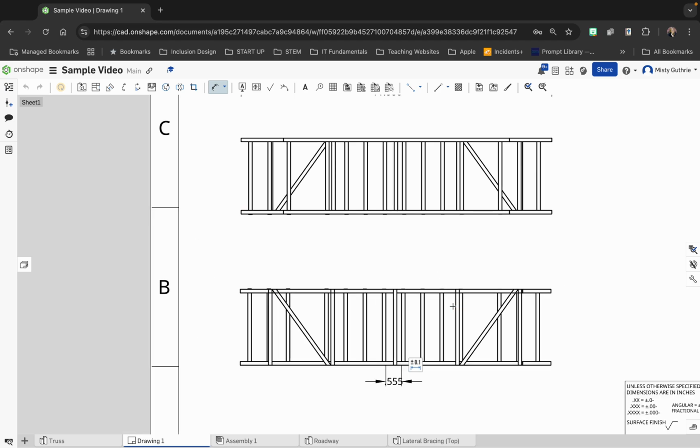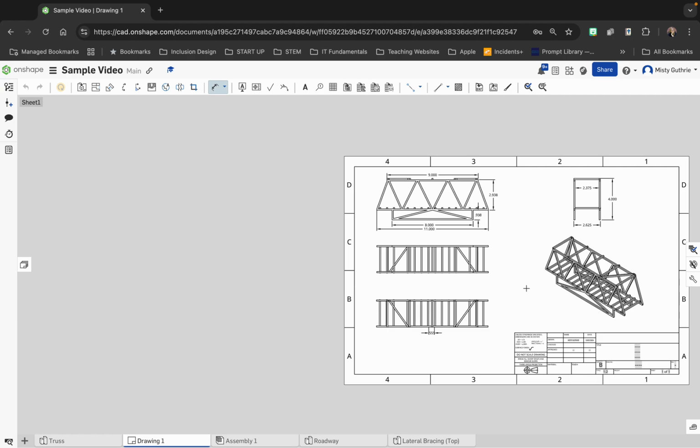Really and truthfully, that is all the required dimensioning that is necessary. Because it's already defined up here as being 11 inches, you do not need to draw it in again. You don't need to do this. It's already been done. But if you felt like this was too cluttered, you could do it on different drawings, just to reduce the clutter.